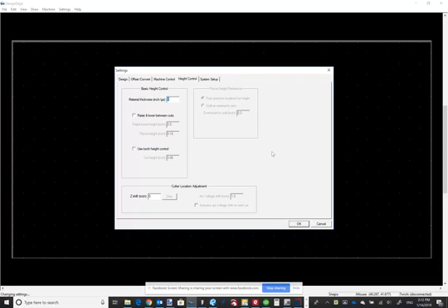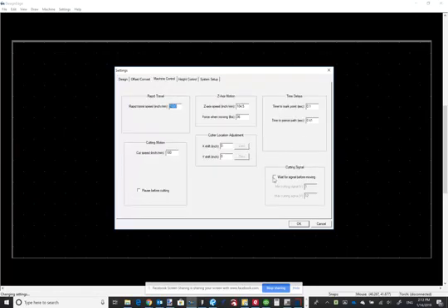Let's see. So on basic height control, you essentially have everything except the ohmic sensing and the material errors that go with it, and then the advanced options that you can change. But if you look back on this machine control, it added this cutting signal box, just like it did when I moved it up to advanced. So either or, you don't have to have both, but either advanced machine control or basic height control will get you that wait for cutting signal box, which will let that pierce time be set to just what it really takes to pierce the metal, without taking into account any pre-purge.